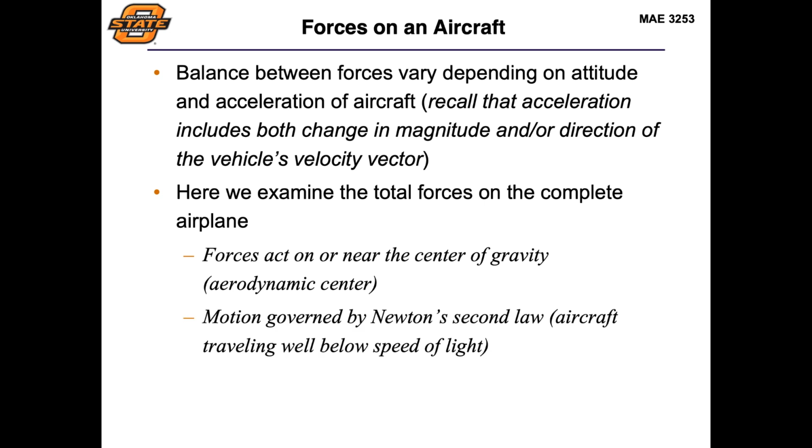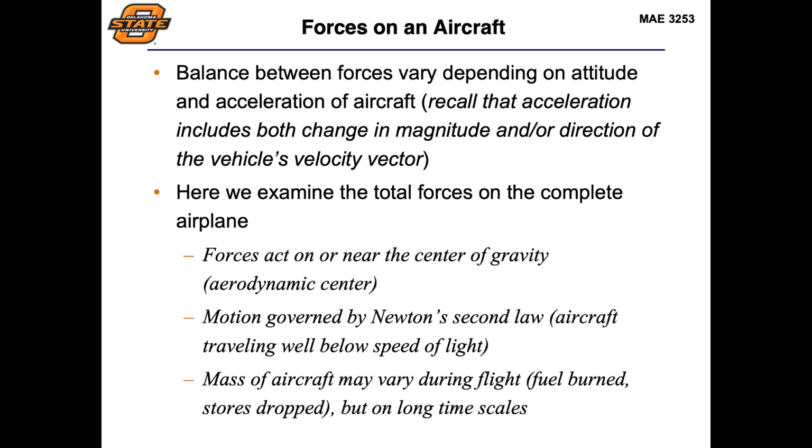Second, all of our motions are going to be governed by Newton's second law. That's obviously going to be true since our aircraft are traveling well below the speed of light. However, the mass of the aircraft may change during flight, and this is important. Even if we have an electric aircraft where we're not burning any fuel, we may be changing our payload. But for all of our aircraft that are operating off of hydrocarbon fuel, our weight will change since we're burning fuel within flight. Now, it is important that even though the mass of our aircraft varies, this is going to be on relatively long time scales compared to the velocity of our aircraft.